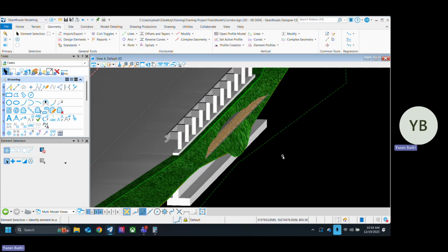Of course, I can also always model the cross culvert in a template. The very first time I did a cross culvert, I did it in a template. We didn't have any of those libraries, like all the pipe libraries, they weren't there. I just did an alignment and I created a square in the template and I ran along the alignment, and that's pretty much all you need, right? So.